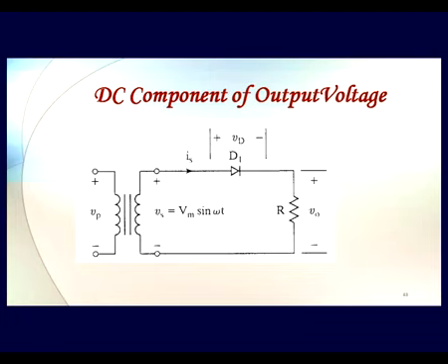How much is it going to be? Let us just calculate with a small mathematics, not very complicated. Consider that we have a circuit of a half wave rectifier where R is the load that we are connecting, across which the output voltage VO is appearing, and VD is the knee voltage that I told you about, that is required by the diode for its own operation, but normally it is so small that we can even neglect it. Now consider that at the secondary we are getting a signal V secondary of Vm sin omega t, where Vm is the peak amplitude of the signal.